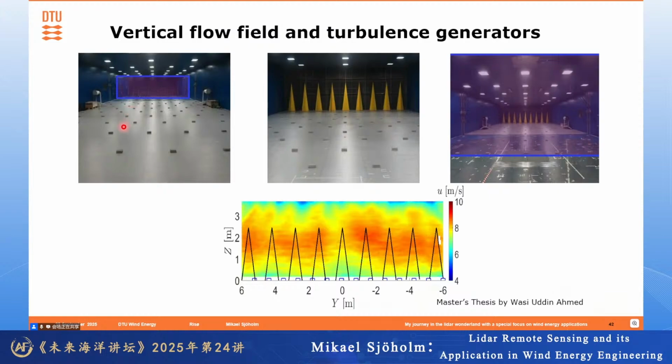Yeah, here is an example of what you can do with these two wind scanners. In this case, you can see them in the left figure here, the two white things, scanning in the big wind tunnel that is 13 meters wide and 30 meters long, I think, and 4 meters high. And you can see all these roughness elements on the ground, and also in the inlet to the tunnel to create some boundary layer.